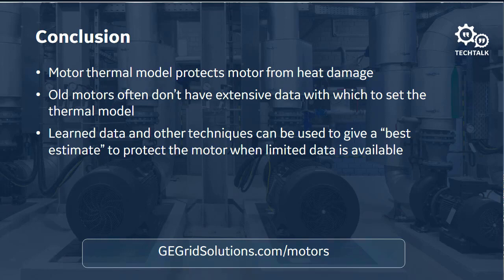If I could fully load the motor to something a little bit less than 100%, then I could observe the current and I could see what the current was at that point, and I could know the pickup. And that might be your best bet in that case. But yeah, that's really pushing it. You're really pushing me to come up with ideas if the nameplate is rusted off. Okay.